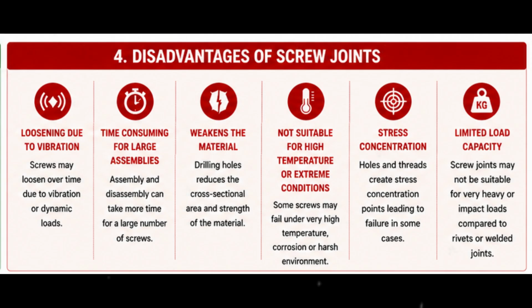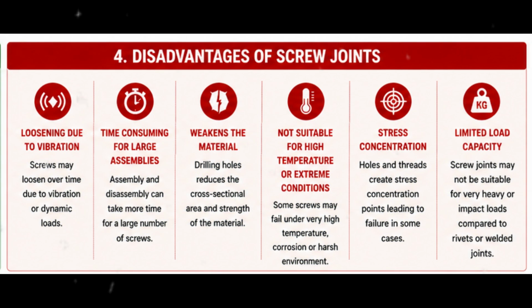For example, in automotive engines, bolts are tightened using the torque plus angle method to ensure correct preload under dynamic conditions. In aerospace, locking mechanisms like safety wire or lock nuts are used to prevent loosening under vibration. This is real engineering practice, not theory.